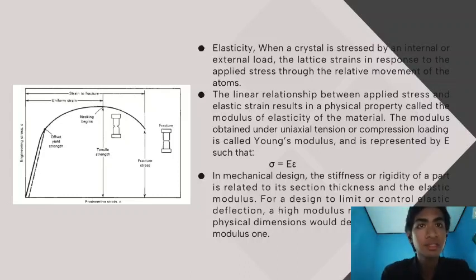Unlike strength, the elastic modulus of metallic materials is very difficult to change by changing the composition or heat treatment. This can be important if higher strengths allow weight reduction with reduced section thickness.